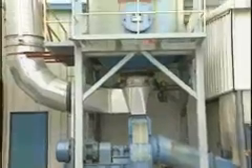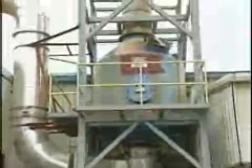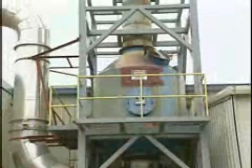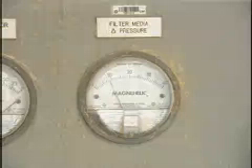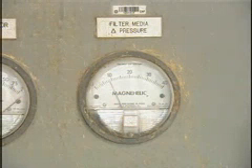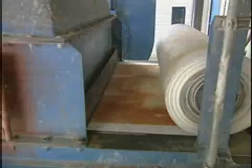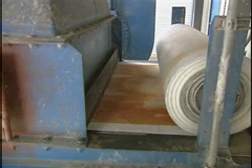These units may have a mist eliminator on the outlet gas stream to capture droplets escaping the filter mat. As the pressure drop across the filter increases, the mat is advanced to expose fresh media to the gas stream. The spent filter mat is disposed of after one use.